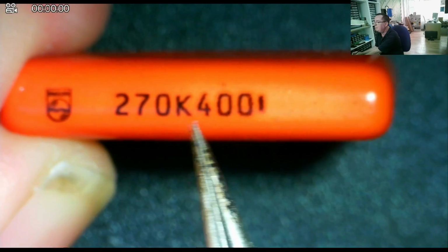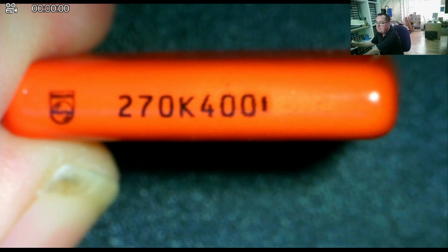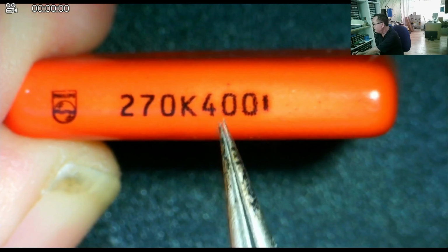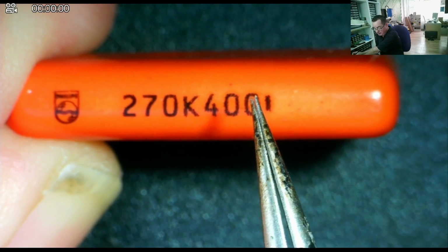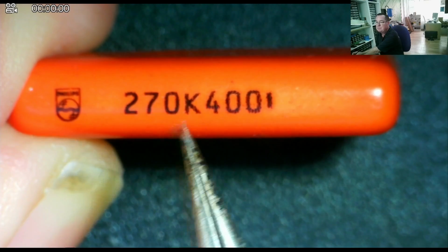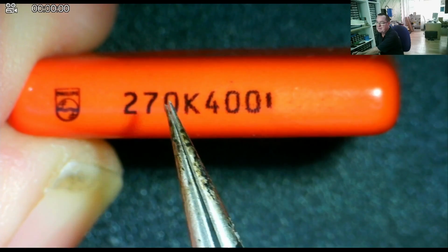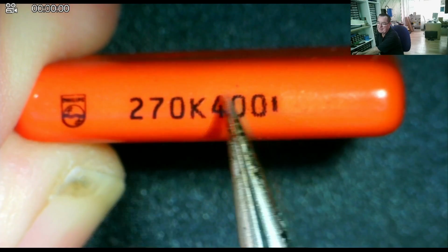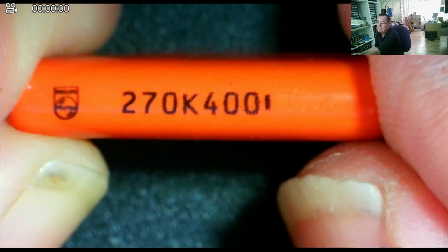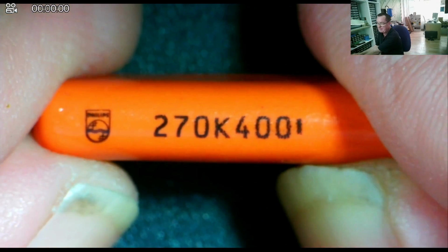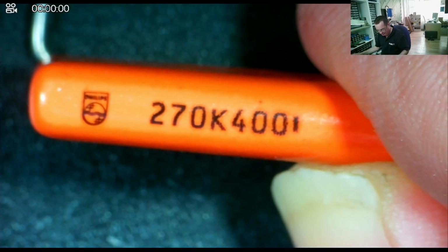This one, 270K. Now this is something I didn't mention earlier, but sometimes you will find this, the K looks like a 1000. But to be quite honest, this is probably a tolerance of 10%. So 270 mentions the value, assumed nanofarads, or you could say 270,000, 400 volt. So you can see, I hope that working out the value of these is fairly intuitive, really. It's kind of like follow your nose to some extent.